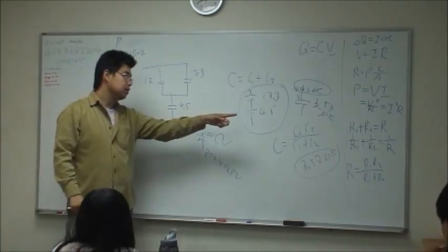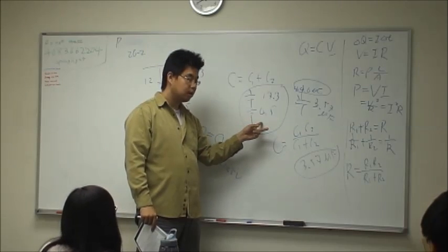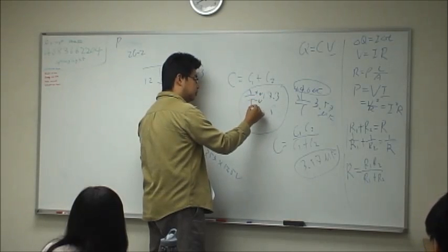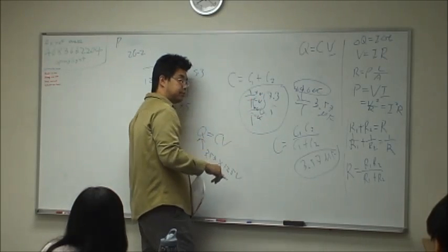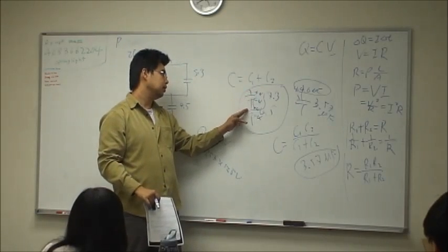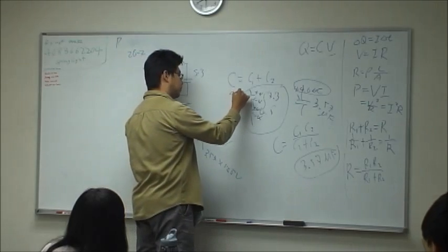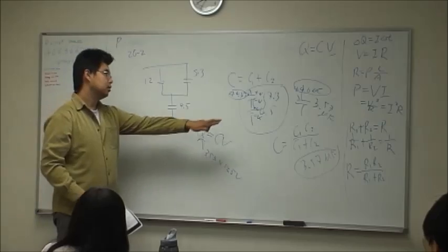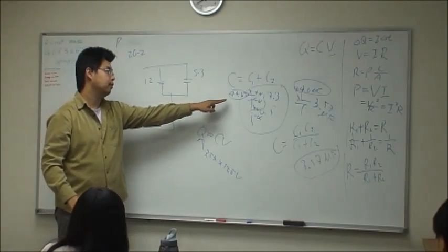Second, this one is coming from what? From two capacitors in series, right? It means on the top is positive Q, negative Q, positive Q, negative Q. So these two are equal to each other and sum to 0. So 44.6 on the top, on the bottom, all of them are 44.6. Here, the top one is two in parallel. The sum of them is 44.6.